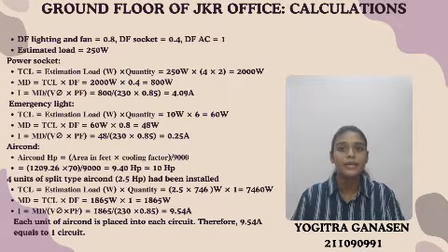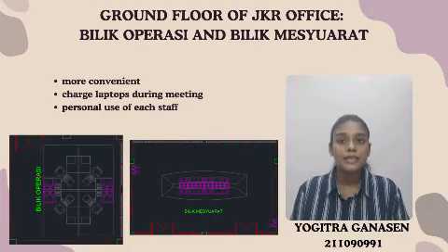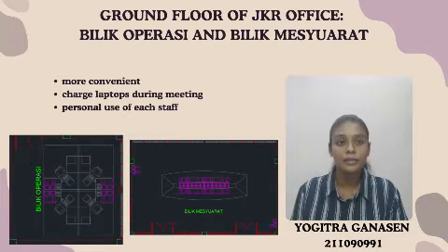For Bilik Mesyuarat, the diversity factor is 0.8 for lighting and fan, 0.4 for socket and 1 for aircon. The estimated load is 250 watt. The 2 times 13 ampere table-fitted power sockets had been used at the operation room and the meeting room.